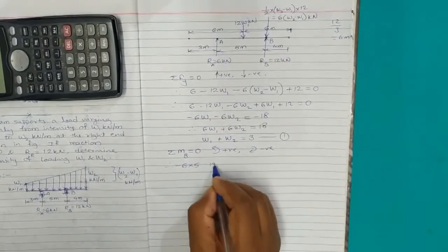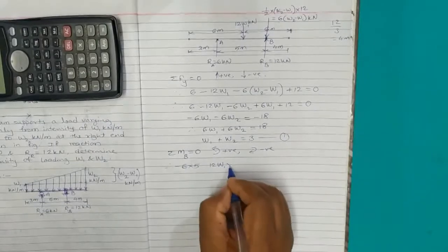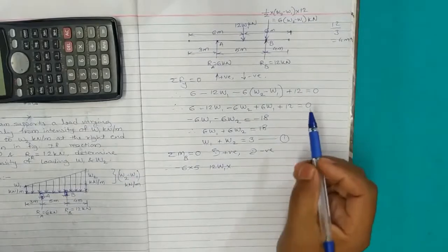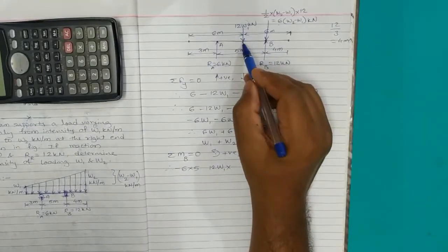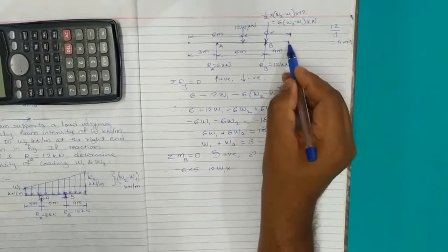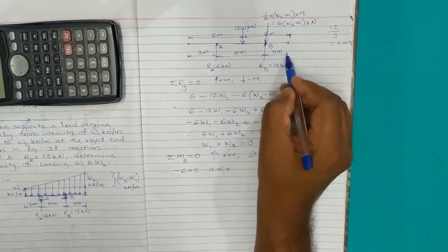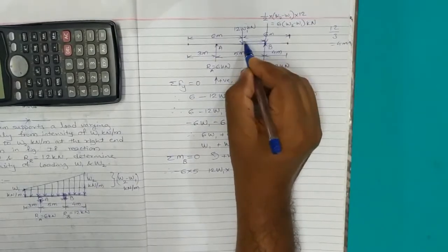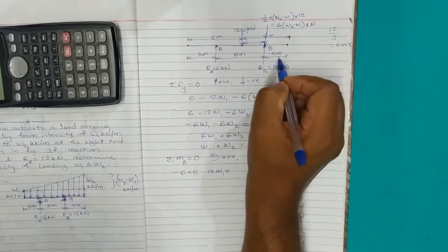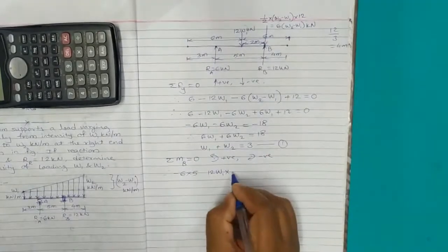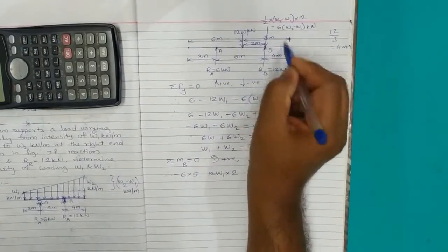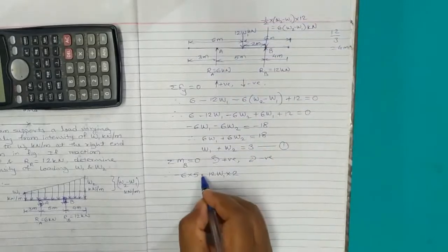Then we have the force 12 into W1. It should be multiplied by the distance. Now, how much is that going to be? Position of this 12 W1 from the end of the beam is 6 meters, whereas from end of the beam up to point B, this distance is 4. So here, this remaining distance from point B up to the 12 has to be 6 minus 4, that is 2 meters. So let's multiply by 2 meter, and the rotation of this load about point B is going to be anti-clockwise, should be taken positive.